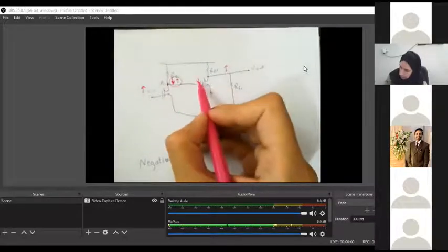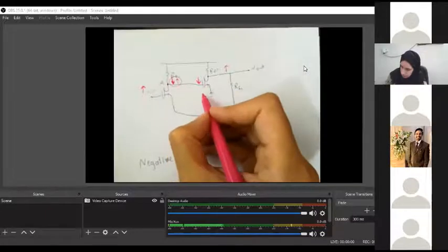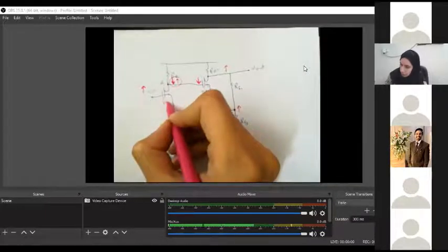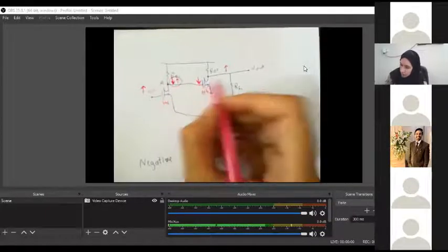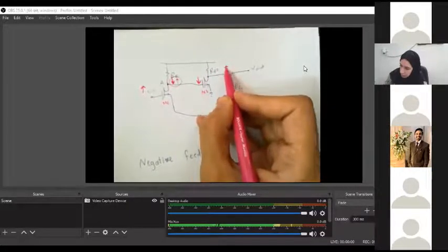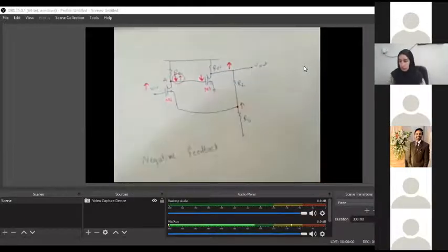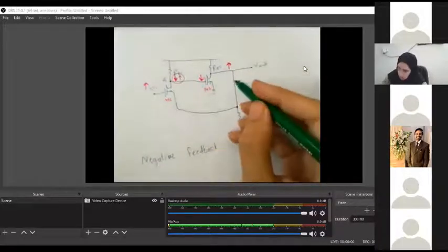and now it's in the gate of another transistor, let's call it M2. This is M1, this M2. Now the gate of M2 is going down, and again checking the drain of M2 is a common source, that's why it's going to go up. Okay, so now V out has gone up, and now this is the feedback path here.